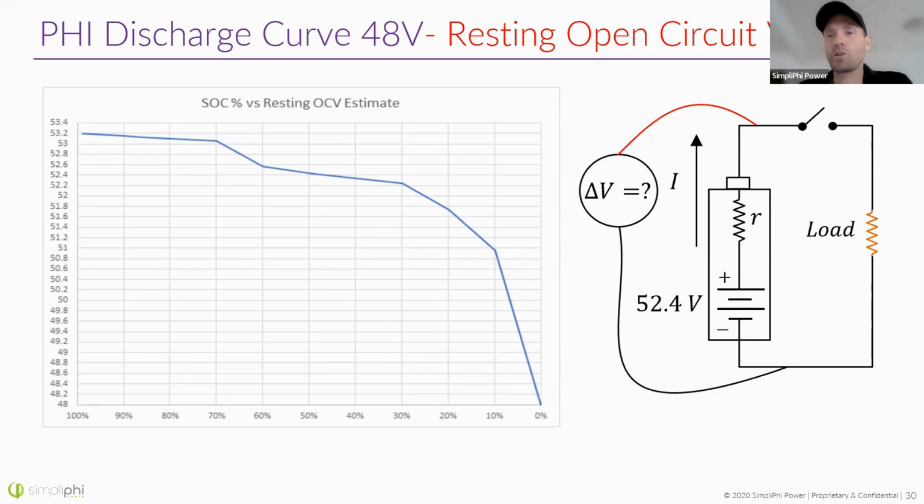Typical float charge amperage: we don't recommend floating the lithium batteries because they have such a low discharge rate. But if you have a renewable energy source, you can float at a 54-volt voltage, and that float charge amperage will vary based on that voltage as the battery reaches closer to 100% state of charge. Less than 1% of the amperage rating of the battery is the typical float charge amperage, and it's really based on voltage. So if you are going to float from a renewable source, float at 54 volts for our batteries.